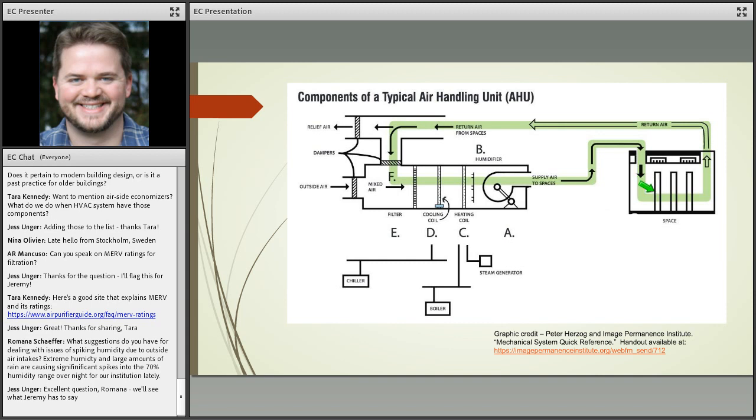And the heat load in the space is what does the rest of the reheat for us. On a hot day, depending on where we're at, we may send 60-degree air into a space that we want to wind up at 70 degrees. That extra 10-degree condition comes from the room itself. It comes from the heat load on the room. So we send 60-degree air out at a relative humidity maybe around 60 to 63%. And by the time it raises the temperature by 10 degrees, we've dropped the relative humidity down to around 50%.